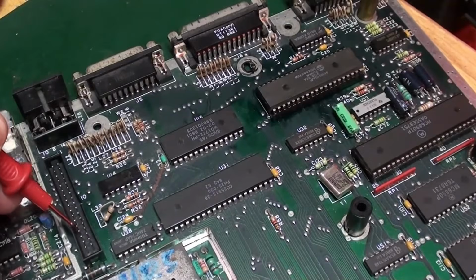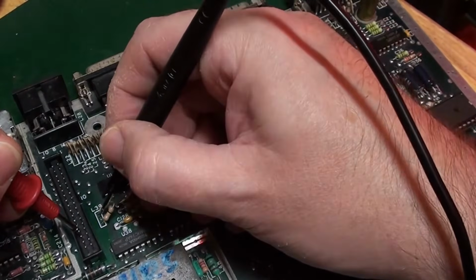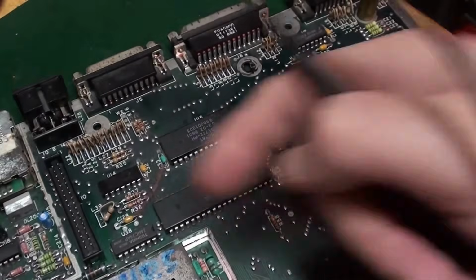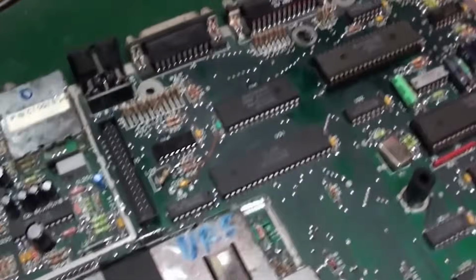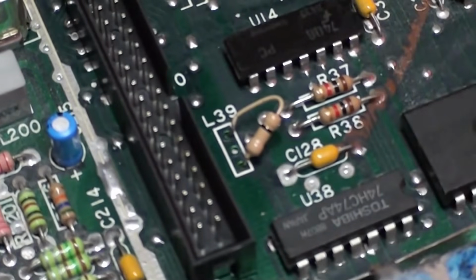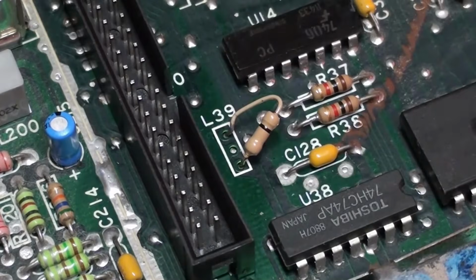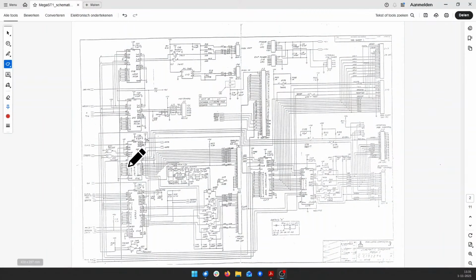I prefer a non-destructive solution. Now I recently saw a video from BW's TechnoShed. This shows jumper pads on an STFM board to switch the drive select on the external drive from drive B to drive A. We can connect a switch to those pads and leave the Yamaha chip in the ST. But does my Atari Mega ST also have those jumper pads? Here's the Mega ST schematic. Are those jumpers here too?